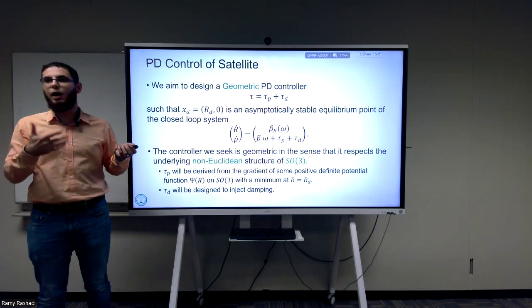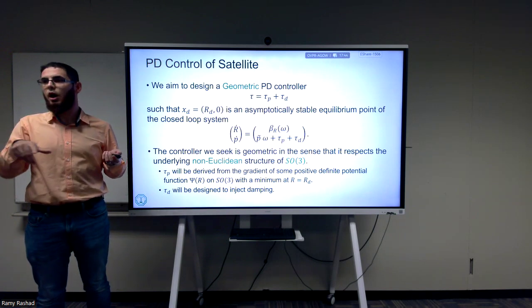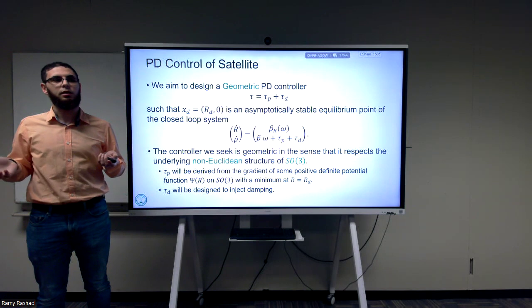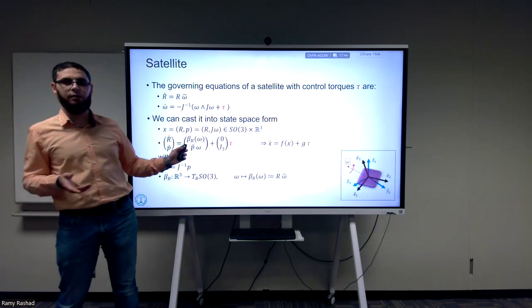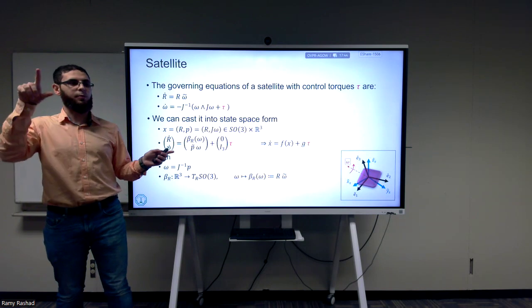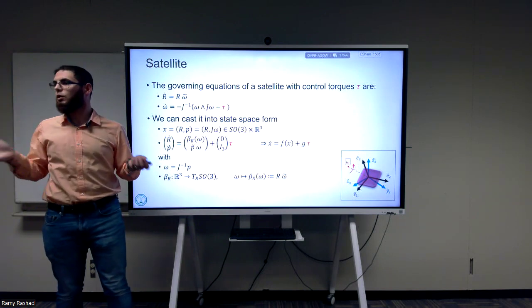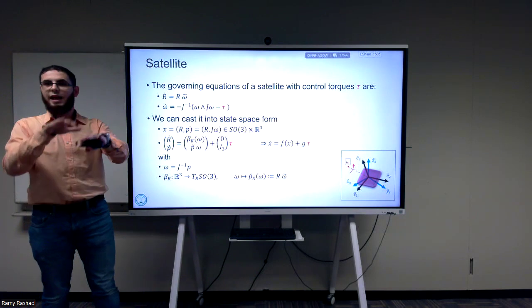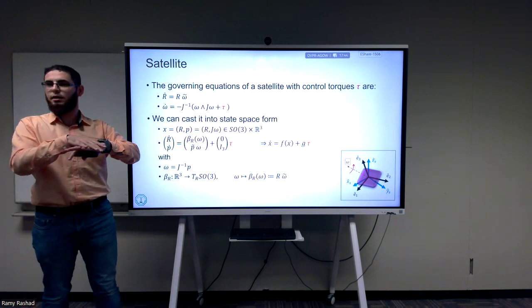Just kinetic energy. How do you calculate this kinetic energy? Half omega transpose J omega. Or written in terms of the momentum, it's 1/2 P transpose J inverse P. Right? They're exactly the same. So you see the analogy between the point mass and the satellite.